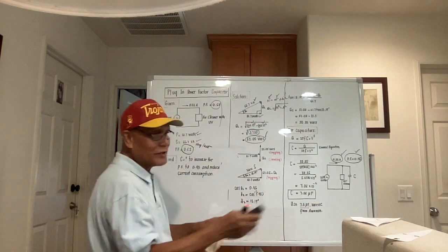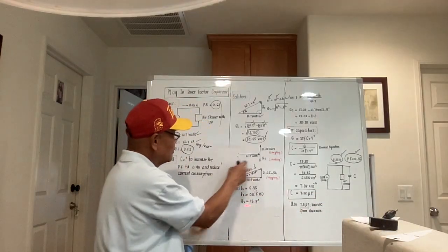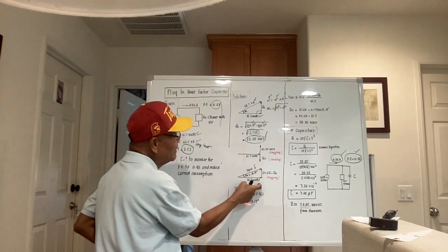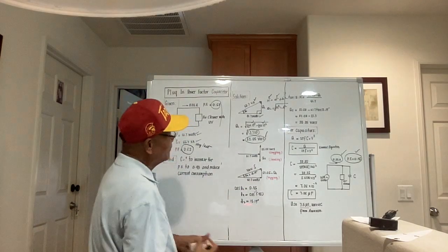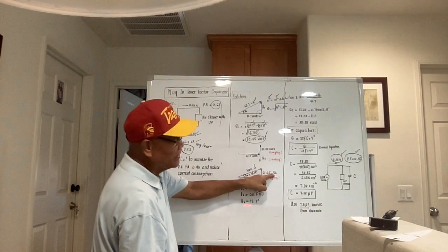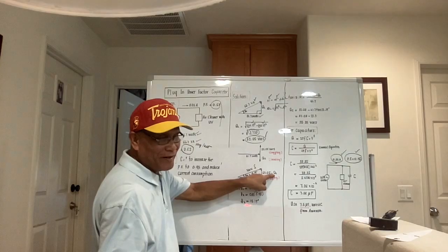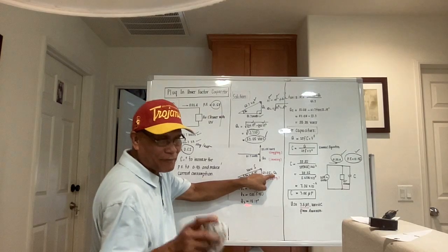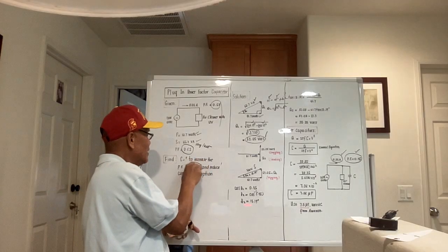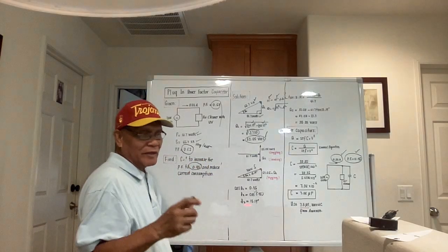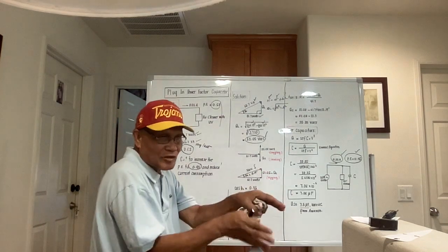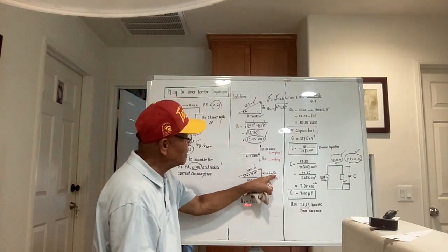Okay? So if we compress this triangle now, this 41.7 is still 41.7. This portion here will be 52.05 minus Q sub C. For the meantime, our power factor is just 95%. That's what the problem is asking, right? 95%. So meaning to say, the reactive power of the motor load still exists, but it is not so much because we are subtracting Q sub C.